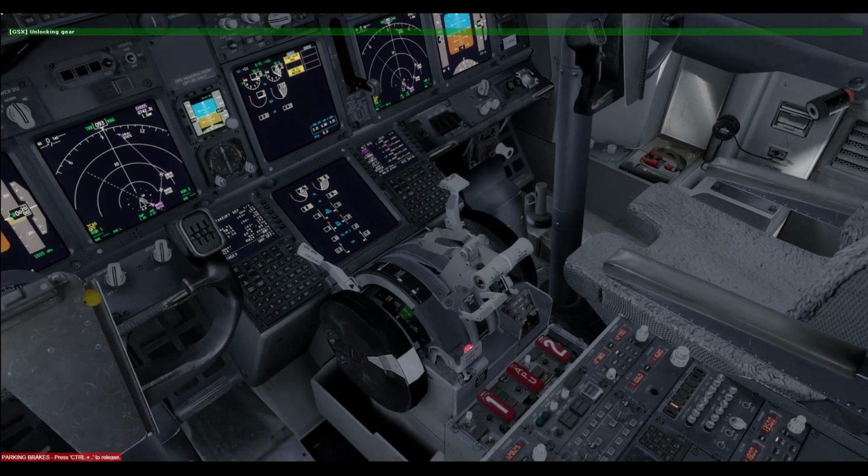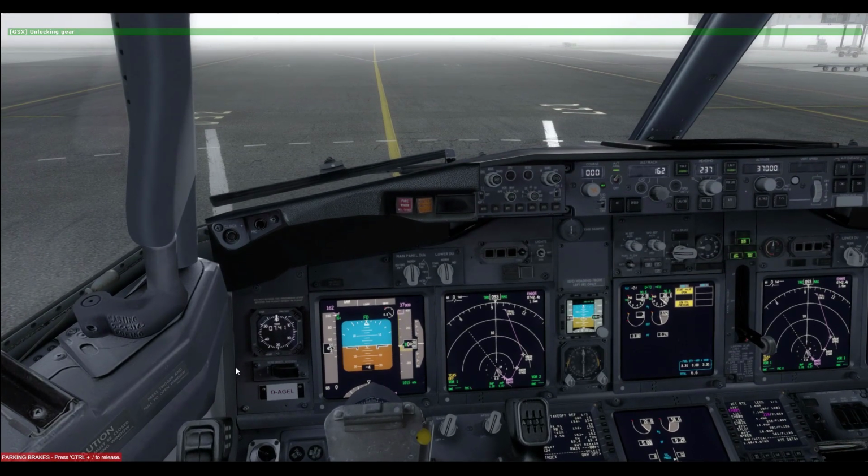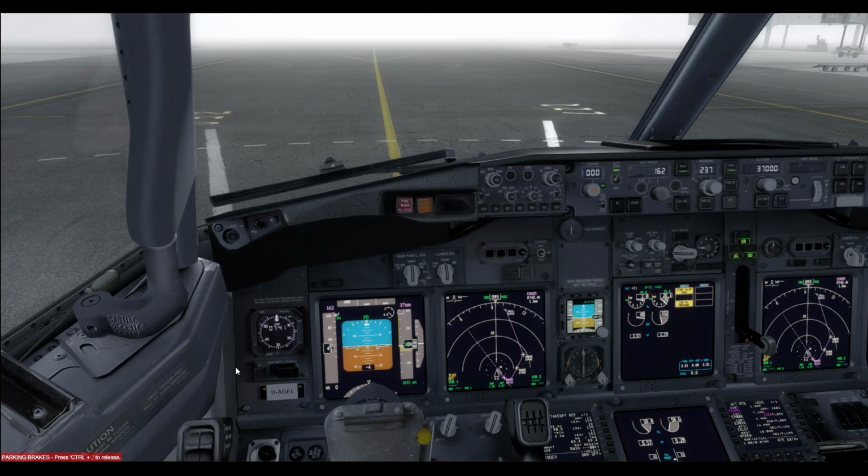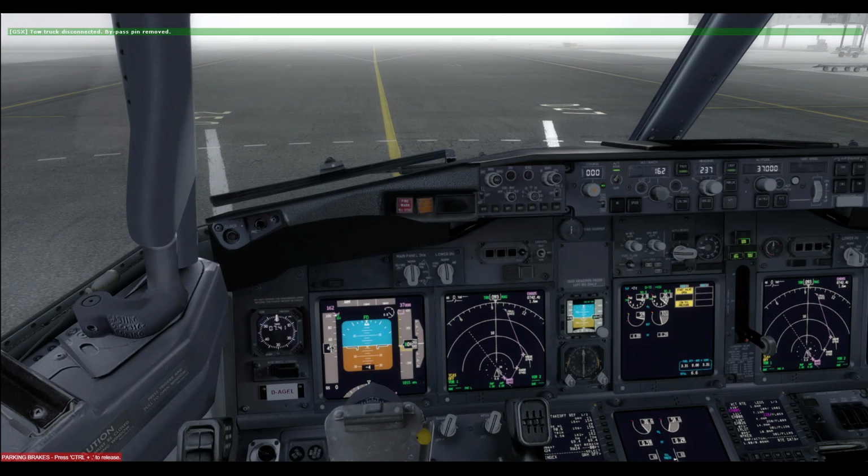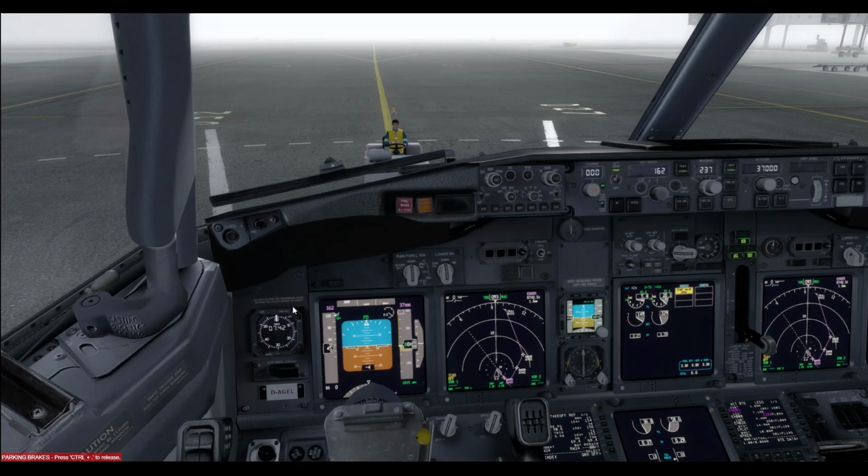Put the fuel in. It doesn't need to be exactly 25%. You should aim for in between 20 and 27. 27 is maximum. Because if you don't put the fuel in, the engine can't really spool up.